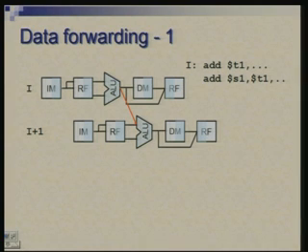the basic idea that if we let this information be forwarded in this manner, then you notice that we do not require to stall the instruction. Okay. The action of writing it into register file will still take place, because maybe some instructions down below also need that. Okay.